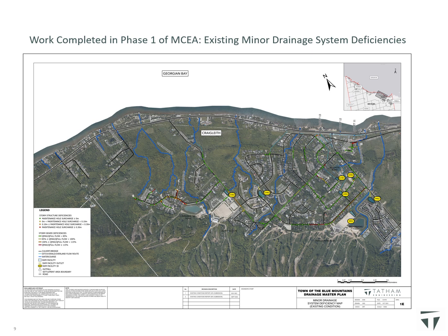The town's storm sewer design criteria were used to identify deficiencies. Specifically, a section of storm sewer has been identified as deficient if the storm sewer surcharges to the roadway during the 1 in 5 year return frequency design storm. Under this scenario, the section of storm sewer has insufficient conveyance capacity and storm runoff backs up through the catch basins in the roadway to the road surface.